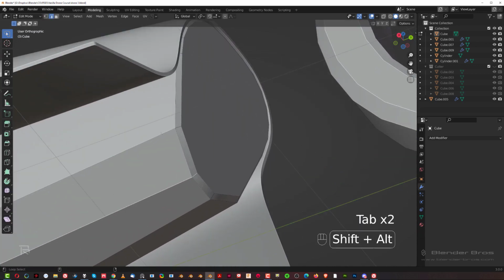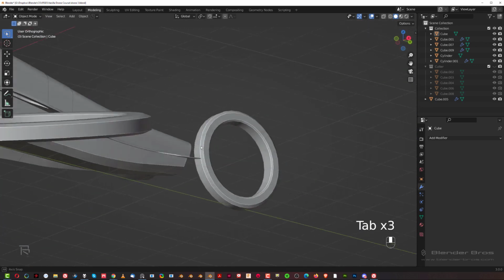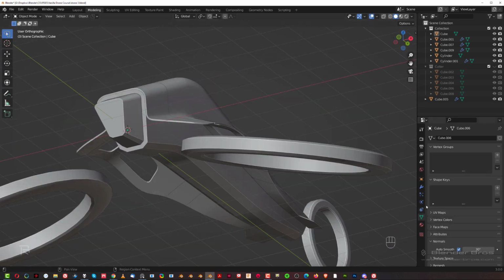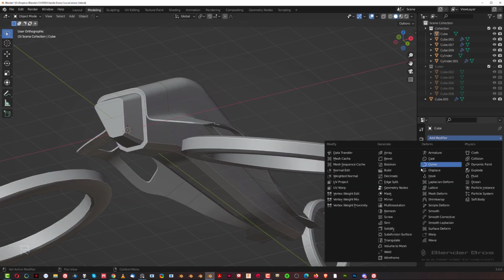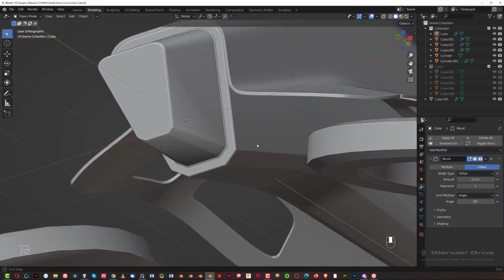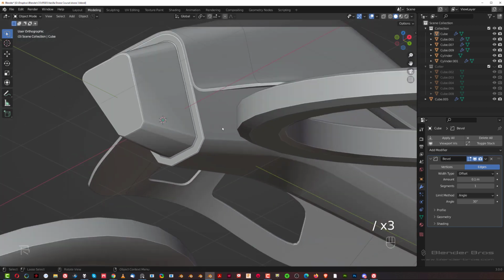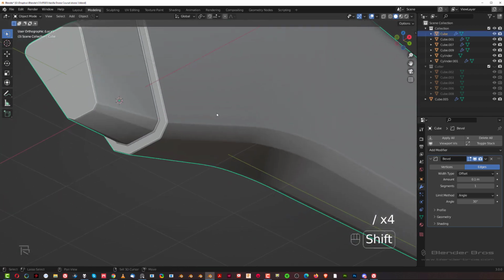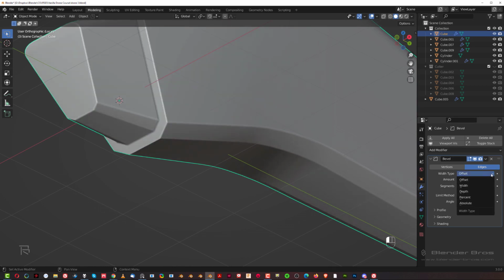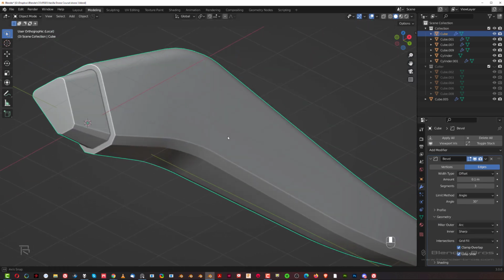And what we could do is introduce some bevel here later on, so it's going to be a little bit more smooth. So let's go here to bevel. Okay. And you can see that it's a mess. Let's go to local view. So let's just select this one, go to local view. And let's first of all introduce 3 segments, and then let's change here amount. Actually, amount is okay. But what we need to do is go to geometry and change miter from sharp to arc. It's going to look a bit better.